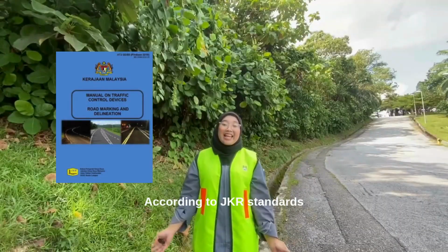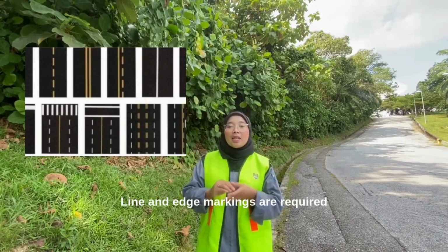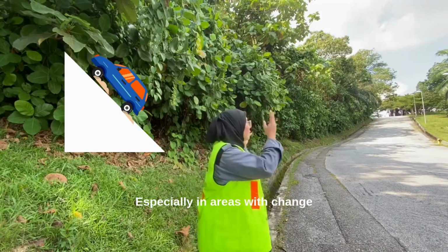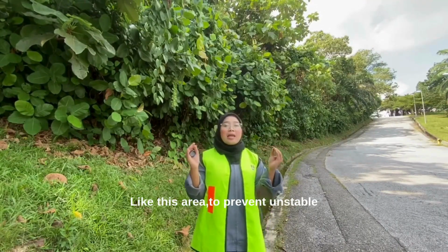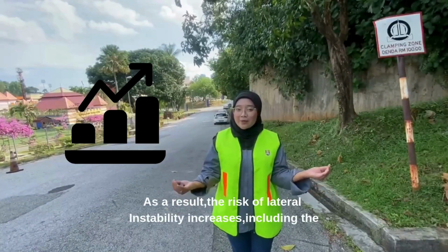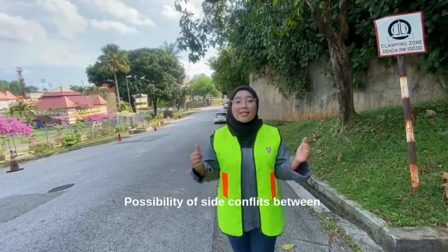According to the JKR standards and common design practice, lane and edge marking are required to provide a clear traffic alignment, especially in areas with gradient changes, such as a downhill section like this area, to prevent unstable vehicle movement. As a result, the risk of lateral instability increases, including the possibility of side conflict between vehicles moving in the same direction.